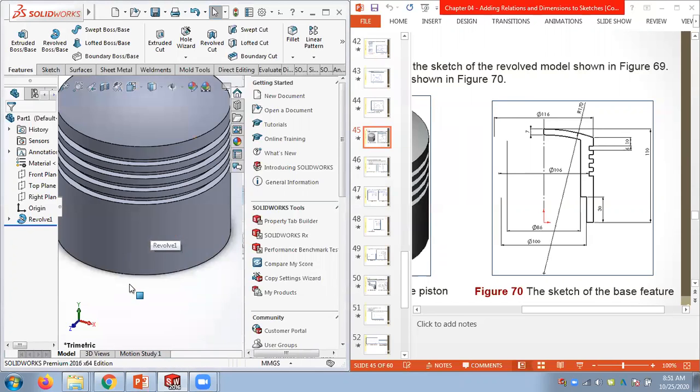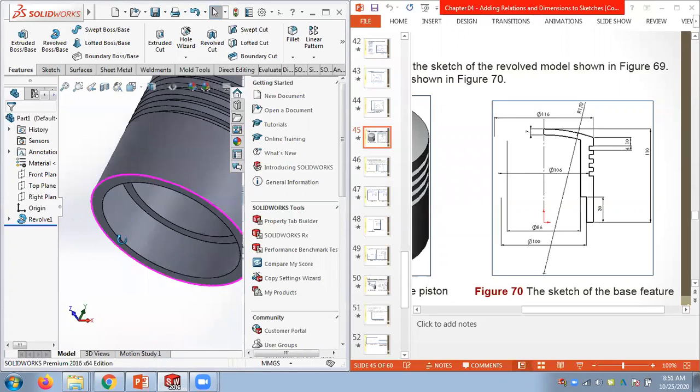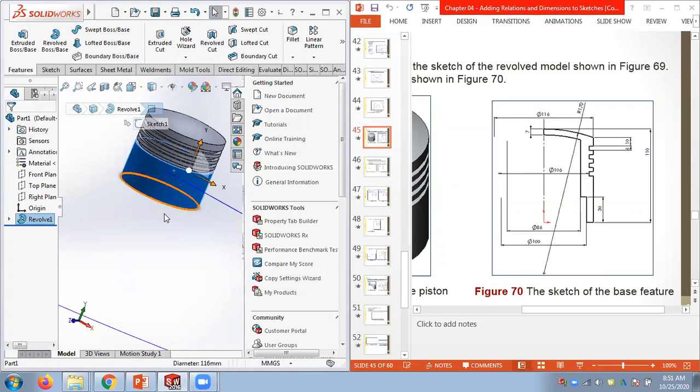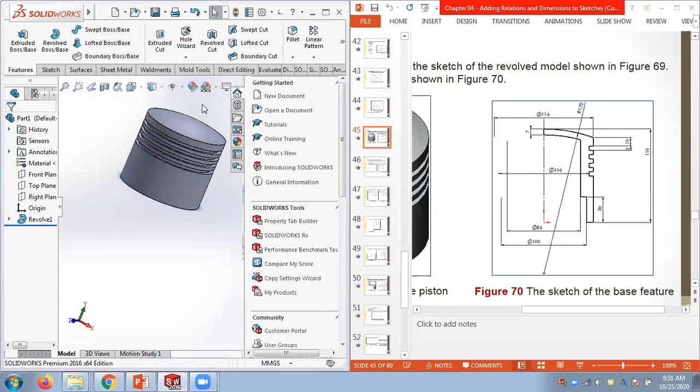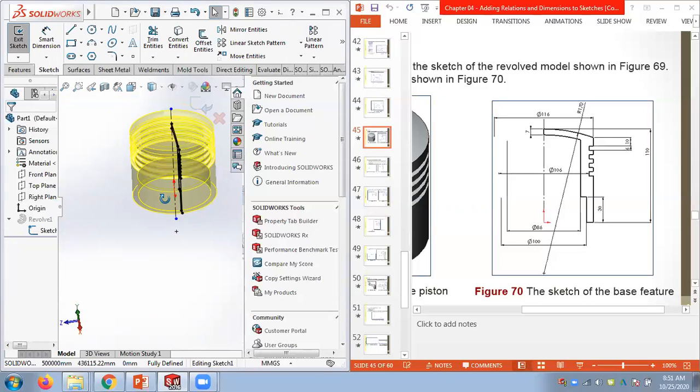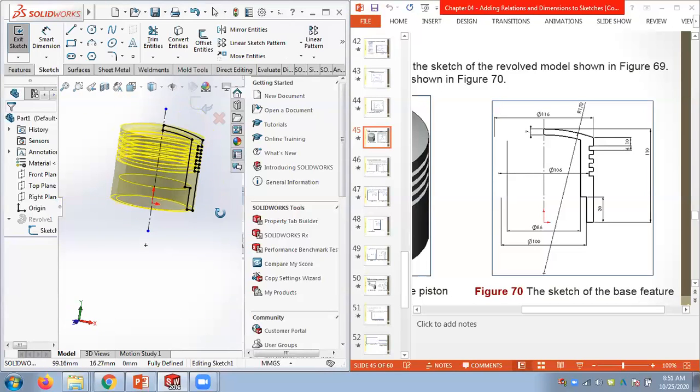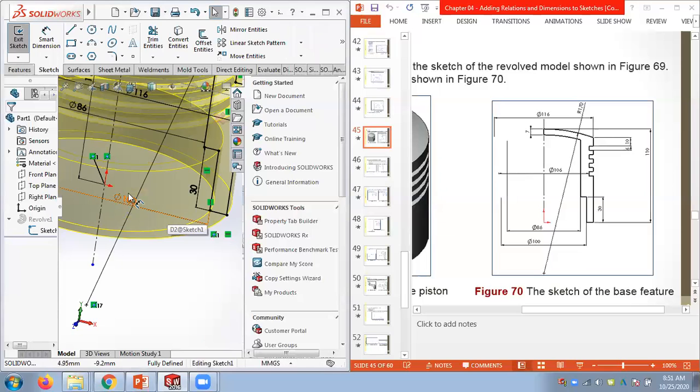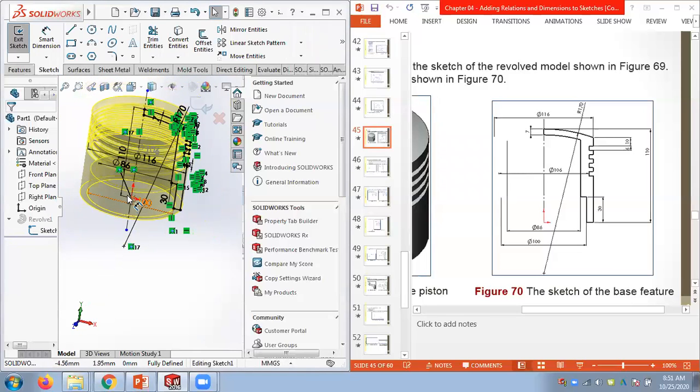These are the outcome. So when I dimension this drawing, I didn't put diameter 100. I just put 100 here. But when you take a manufacturing drawing, you need to put diameter 100. This sketch is only for SolidWorks. These dimensions are not for production drawings. So diameter is automatically put by the software. So I didn't put it manually. So he has done it for me. So this is the whole idea.